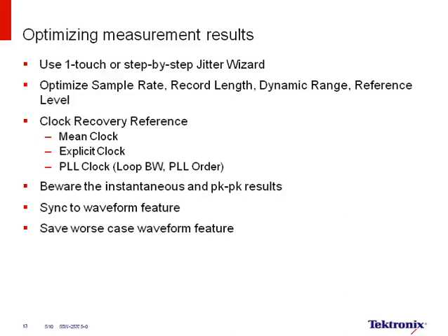For example, customers will have situations where, depending on what they set the record length to, they will get different results. So a very common occurrence is that when you go from, say, 1 meg record length to 10 meg to 100 meg, you might get a larger TJ.